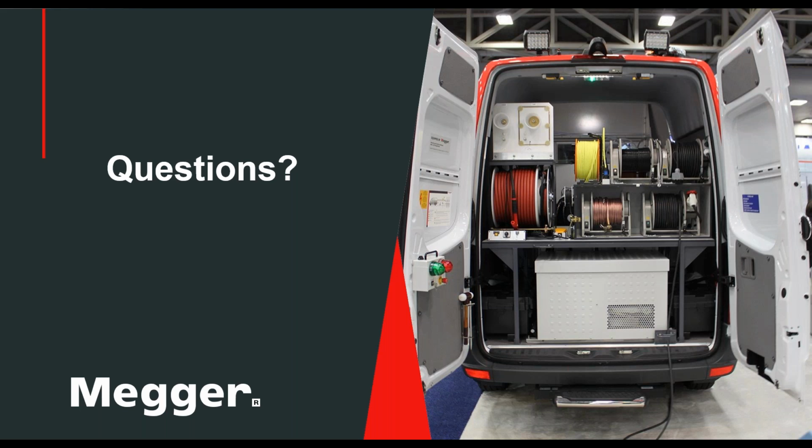Now, whether it's PILC cable or any other cable, the general rule is, once we've done that breakdown test, we want to use the lowest voltage range available to us. That will provide the largest amount of capacitance, and that's going to give us the largest joule number. And then I guess the question was specifically about PILC cable.